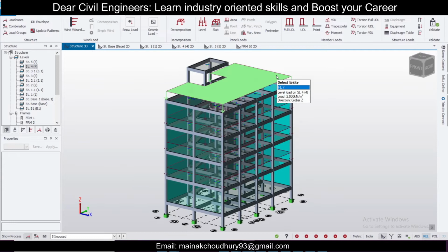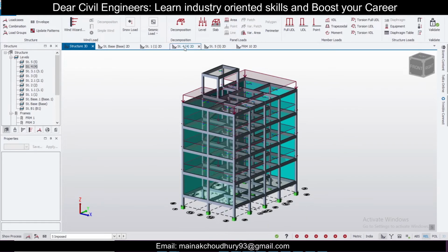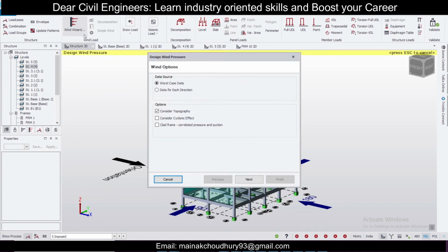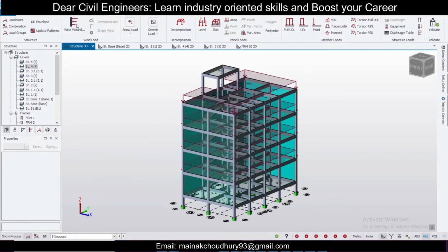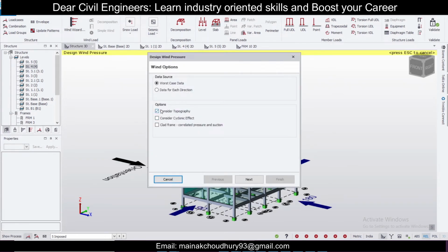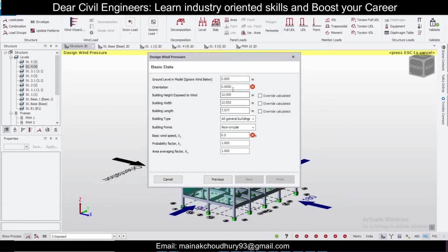After that, you just need to go to this option of the wind wizard for the wind load, click on this wind wizard and consider topography. You're going to click this worst case data, next, and orientation. If this comes across, then you can click 90, or if it doesn't come anything, then you can stick to 0.